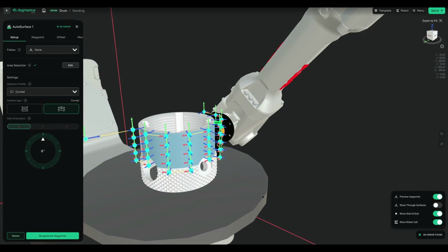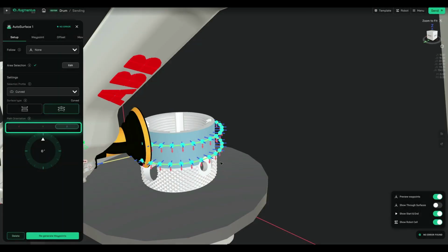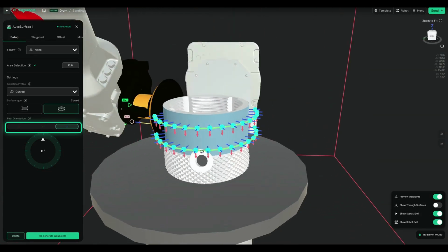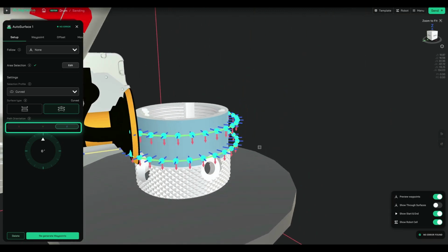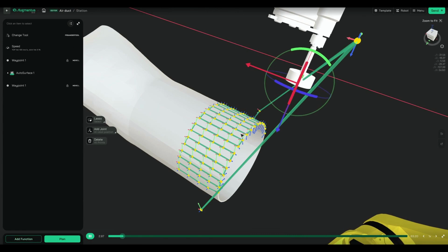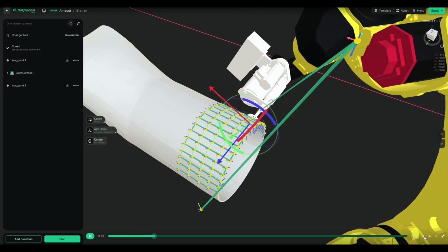On a cylinder like this drum, choose the curved profile and the axis selector appears. It sets the direction the algorithm slices the surface. On the x-axis, the passes run straight along the drum. Switch to Z and they wrap around it instead. Pick the axis that follows the length of your pipe, tube, or channel. That's the whole setup. Everything else works just like the simple profile walkthrough.